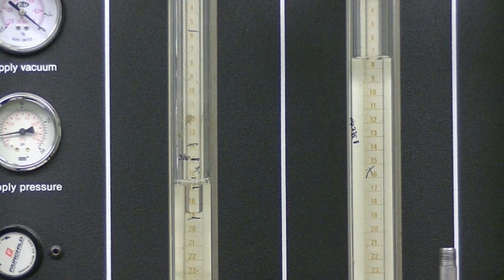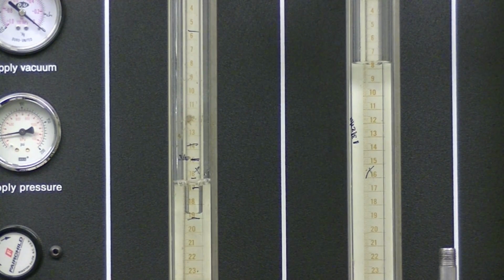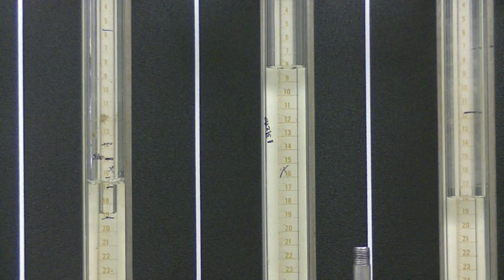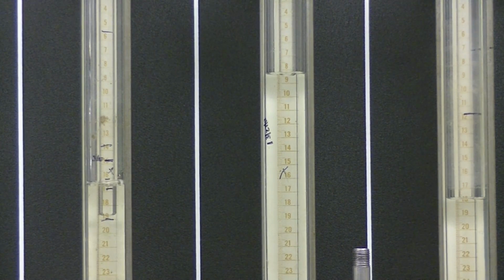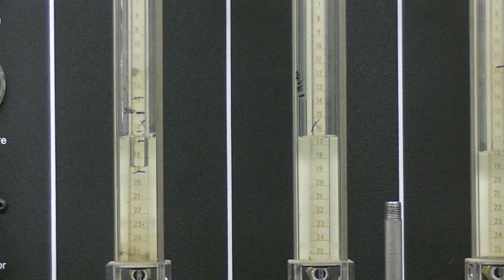Increase the hydraulic head in regulator 2 so that the water level in the manometer is above that of regulator 1. Allow draining to occur. Notice the hydraulic head is decreasing in regulator 2 and increasing in regulator 1. Thus, water is flowing down from the manometer and into the bottom platen, through the specimen, and up into the